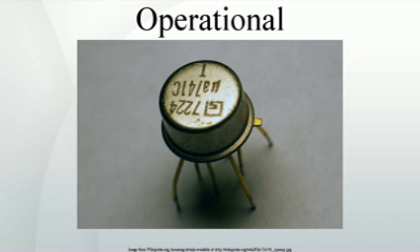Historical timeline. 1941, a vacuum tube op-amp. An op-amp, defined as a general-purpose, DC-coupled, high-gain, inverting feedback amplifier, is first found in U.S. Patent 2,401,779, a summing amplifier filed by Carl D. Swartzel Jr. of Bell Labs in 1941. This design used 3 vacuum tubes to achieve a gain of 90 decibels and operated on voltage rails of ±350 V. It had a single inverting input rather than differential inverting and non-inverting inputs, as are common in today's op-amps.